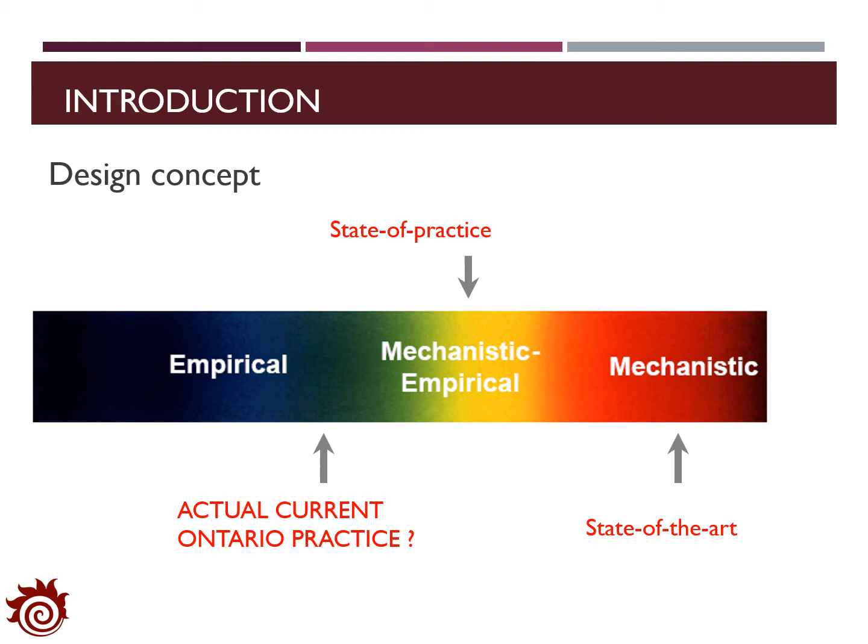In the empirical model, the field experiment data will be applied, and we will use the statistical model to find out the material selection and the determination of the pavement thickness. However, this model cannot reveal the impact of the traffic load, climate conditions, and drainage conditions. On the other hand, the mechanistic model has the advantage of analyzing those impacts. However, this model is generally applied for some simple situations, and it will be very complicated for the real-world implementation